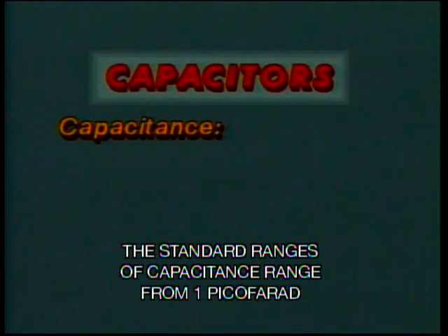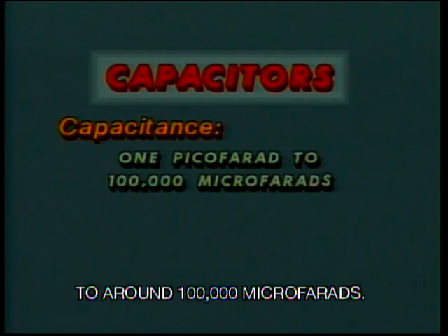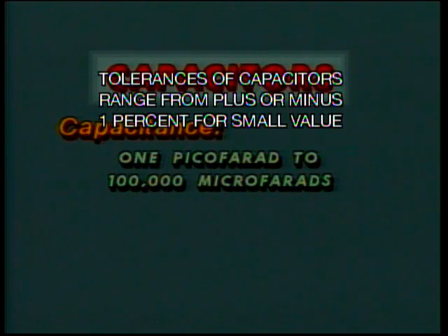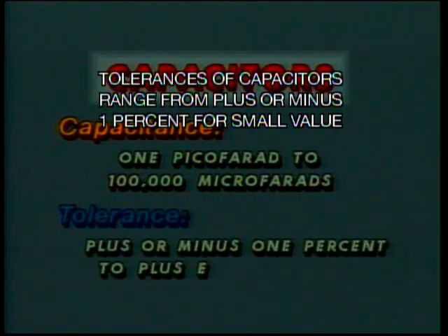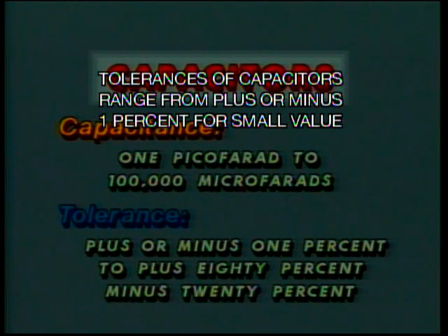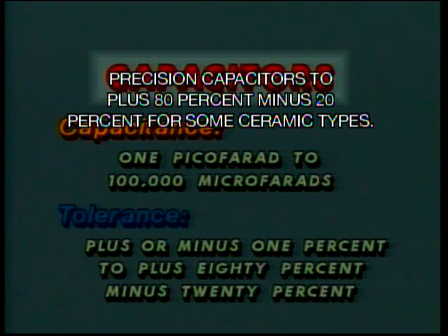The standard ranges of capacitance range from 1 picofarad to around 100,000 microfarads. Tolerances of capacitors range from plus or minus 1% for small value precision capacitors to plus 80%, minus 20% for some ceramic types.